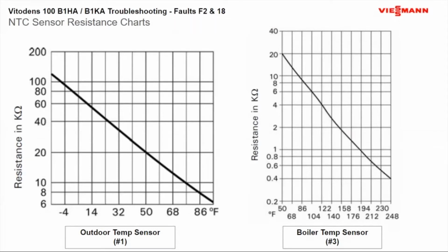As you can see here, here are our resistance charts that we do have in our manuals. So that's why it's nice to see the manuals and have the manuals on site if you can. That's why I always show that pro resources, so you can have these sensors, because this is the way you test your sensors, by doing ohms tests on them.